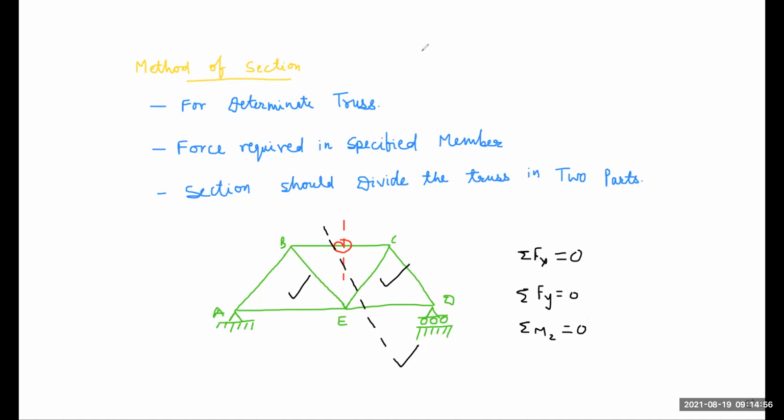So it's your choice whether you choose this portion or that portion. Next, the member in which the member force is required must be cut by the section. Keep this point in mind: the member in which member force is required must be cut by the section. So these are all about your method of section.